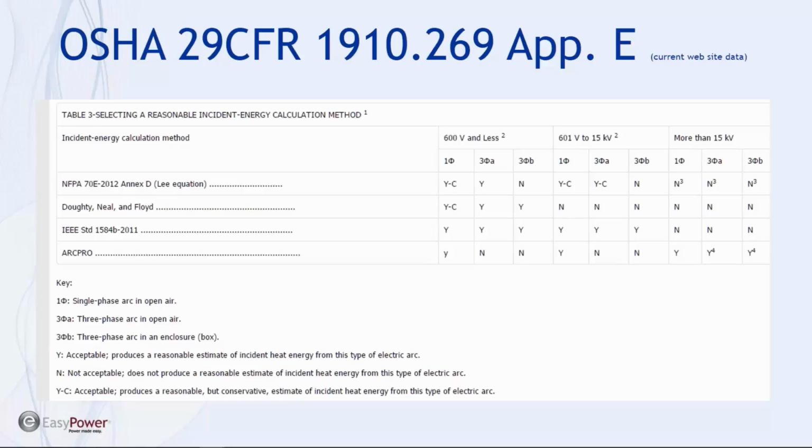From what I've seen of it, it's a DOS-based analytical tool that will calculate heat flux, but you still need to be able to predict the trip time, which you cannot do with the tool. And so you'll need EasyPower to be able to calculate the trip time of a breaker or a relay, and to be able to use the data.